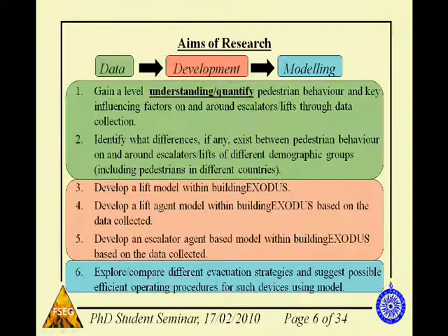So my research can be split up into three parts. There is the data collection phase, where we've tried to gain an understanding of how people would behave on and around lifts and escalators during an evacuation, and we've tried to quantify this behaviour. Based on the data we've collected, we've developed a series of models within the Building Exodus software to represent the behaviour. We've also run a series of modelling simulations to see how different human behaviour will influence different operational strategies.